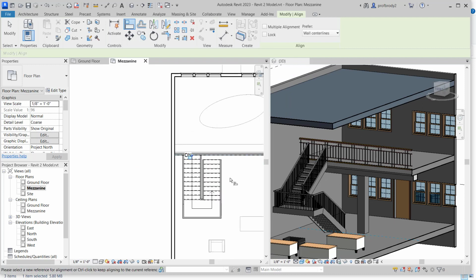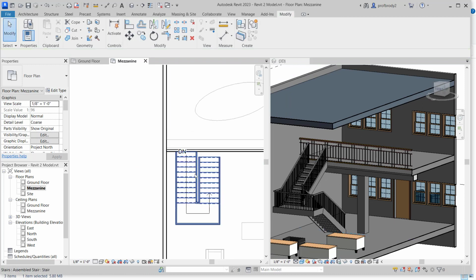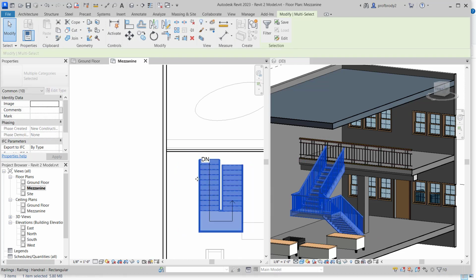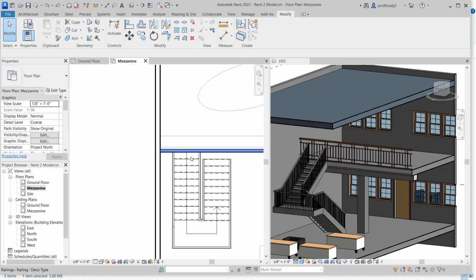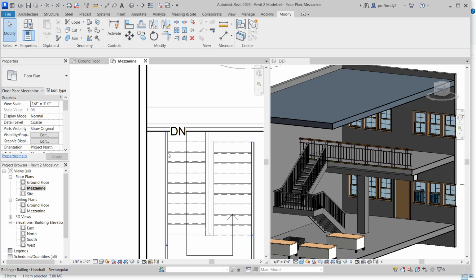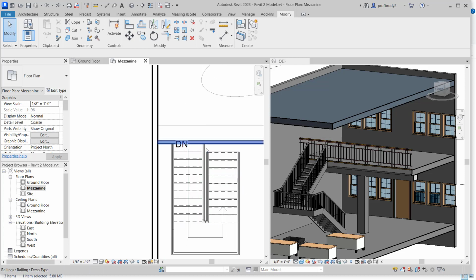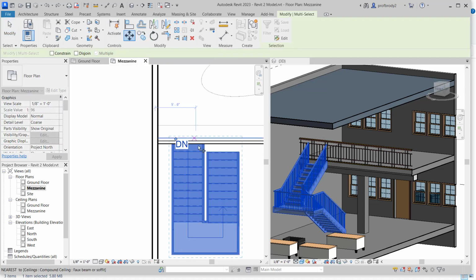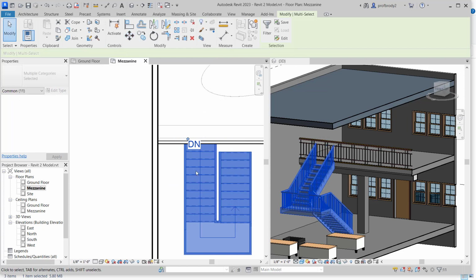By the way, when you have used the Align tool, be aware that now if I move this and just click and drag to move, which we all love doing, you can easily mess up the alignment. So once I've used the Align tool, I either use it again if I want this, say, against the outer wall, or I use the actual bona fide Move tool, not just the click and drag tool. That way you can move something some exact dimension.